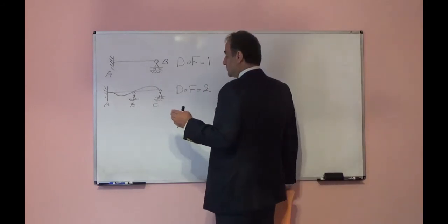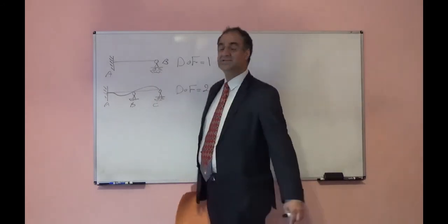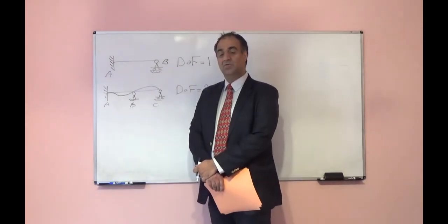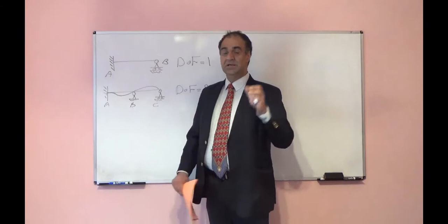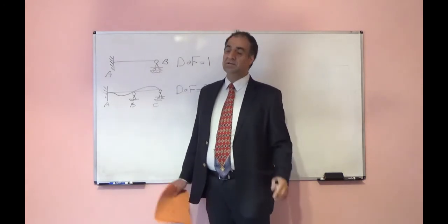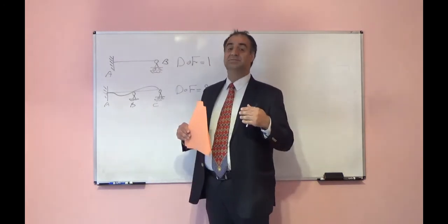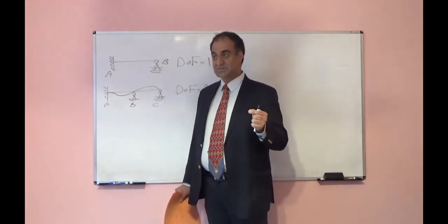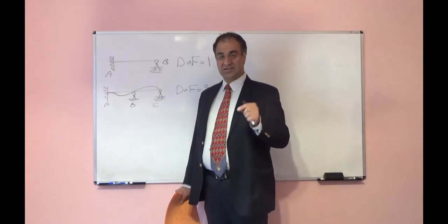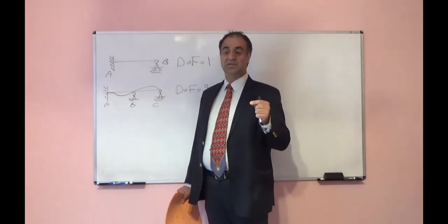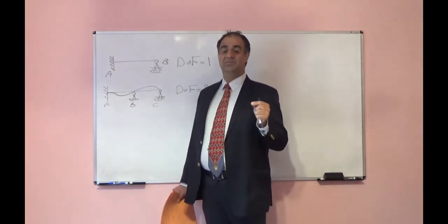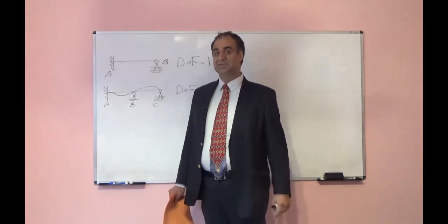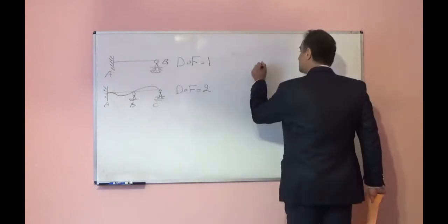In order to find lateral deformation of the structure, convert all joints to pure hinges. Then your structure will be unstable. Find the minimum number of members you can add to that system in order to make it stable. That will show you the number of independent lateral deformations. For example, this way.